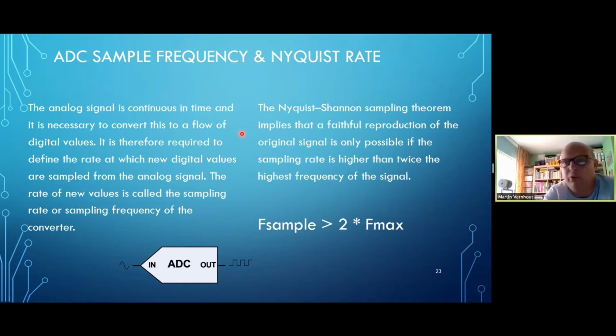And there is always a downside. If you sample faster than fast enough, you have more data, so you need to compute more. Other problems are that if the bandwidth of your input circuit is higher, you get more noise, and you probably pay more for a fast digitizer than for a slow one.